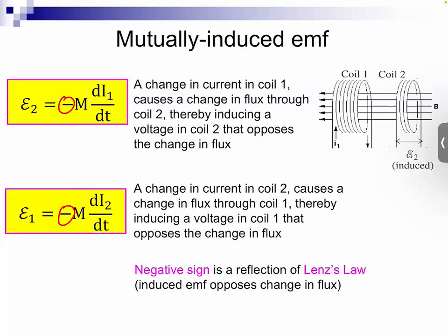And so that's carried over in these definitions here, meaning the voltage that's created in coil 2 because of the change in current in coil 1 is a consequence of Faraday's law, and the direction of current produced in coil 2 will depend on whether the current in coil 1 is increasing or decreasing.